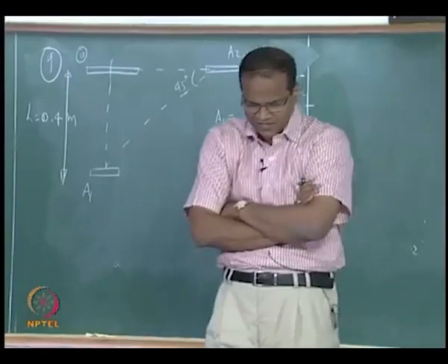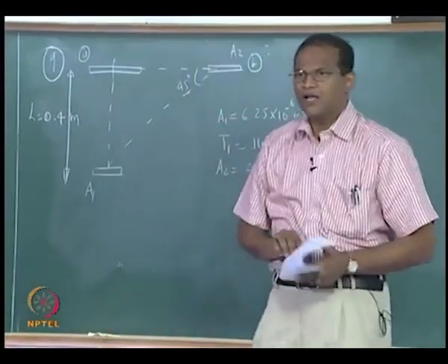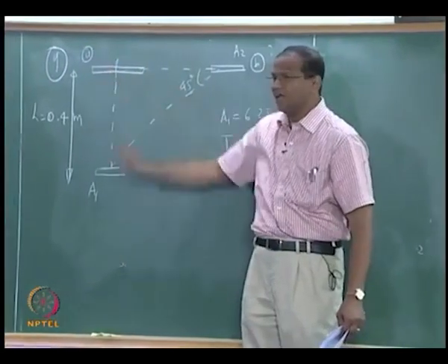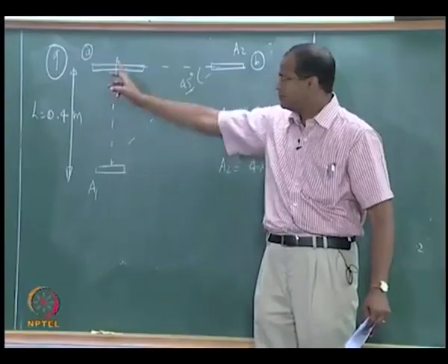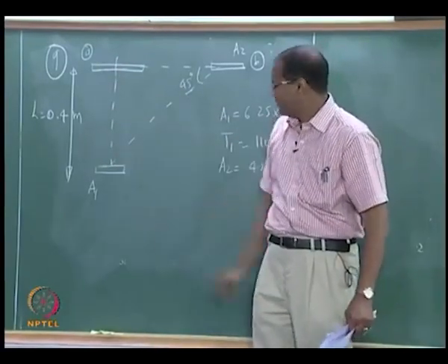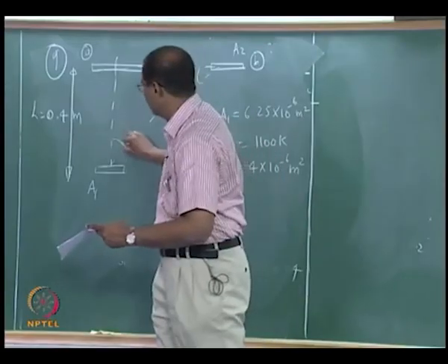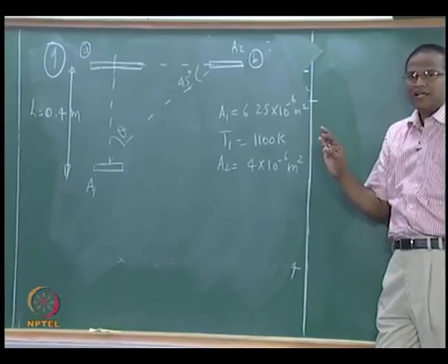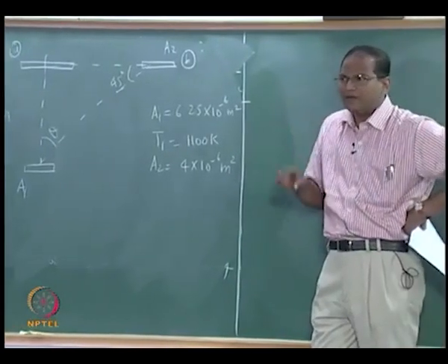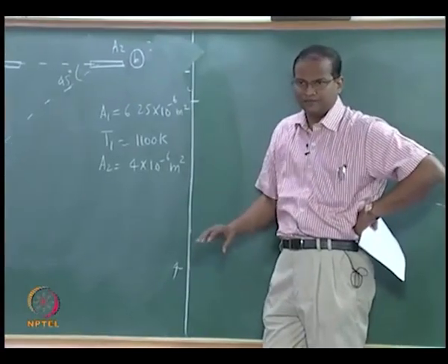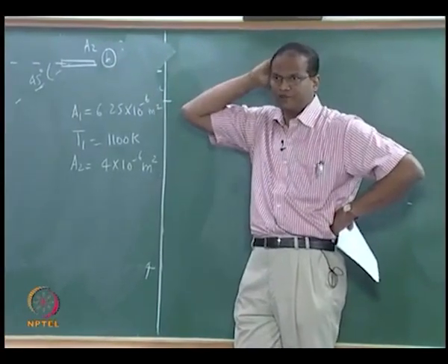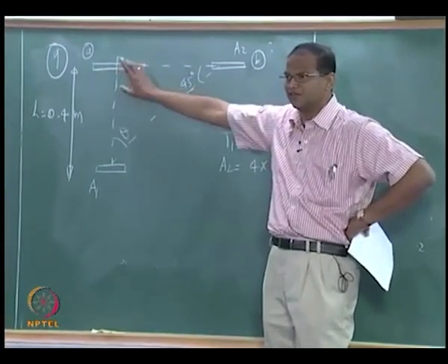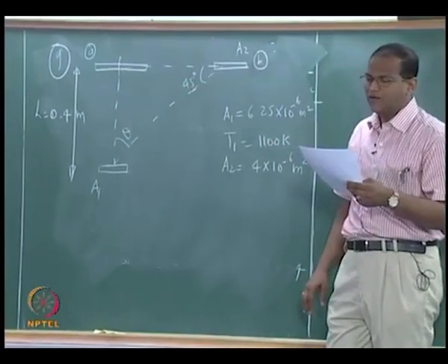A2 is the one that is receiving the radiation, okay. Now when it is at position A, then it is normal, right, it is normal, and this is your theta. When it is normal, it is intercepting some radiation power which can be measured. I have an instrument to measure that, I will give you that value. From that value you will be in a position to find out what the emissivity is corresponding to theta equal to 0 for this surface. Are you getting the point?